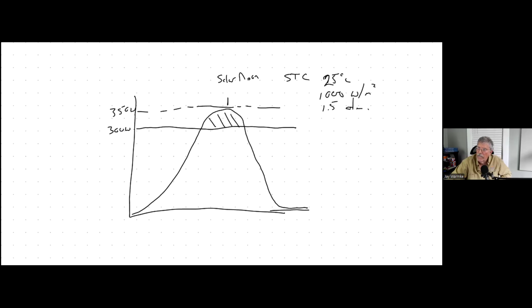So this is simply clipped off. So you lose that amount of power each day on a perfect day. But what if I then put in a 300-watt solar panel rather than a 350 just to avoid that clipping? Well, my curve is going to look something more like this.